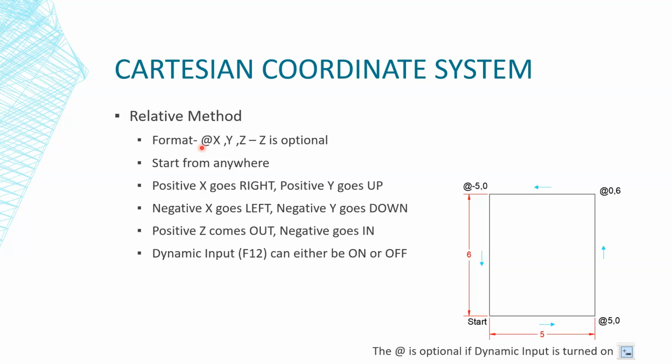Now, by default, when we get to looking at AutoCAD and we look at the line command, with all of these creating or draw commands, the first time you activate the command, the first thing it's going to ask you for is a coordinate. One of your options is that you can type in numbers. That is going to be an absolute value, believe it or not. So with most of these commands, the first thing you're going to do is either type in absolute coordinates, or select anywhere on your screen. So you're going to tell it where to start from. And that's going to be one of the kind of hidden features of it. So I know I say the absolute means that you have to know where every single point is, or you can know where the first point is. And I hope that I'll be able to explain this more when we get to AutoCAD.